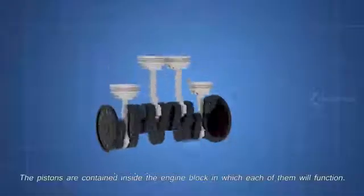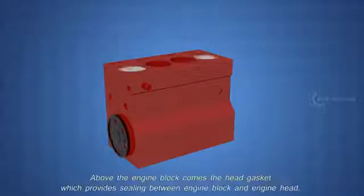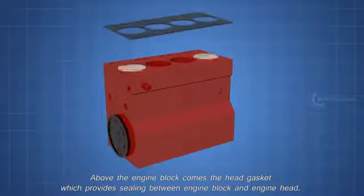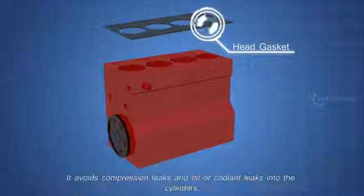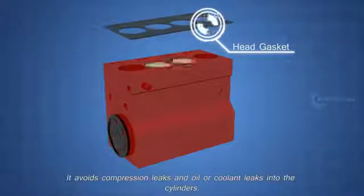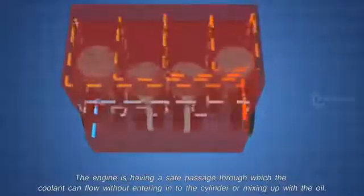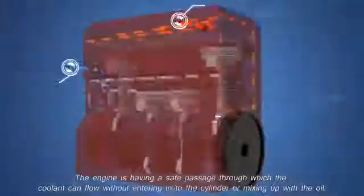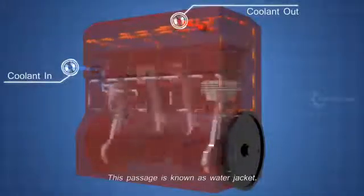Now, let's see how these parts work together. The pistons are contained inside the engine block, in which each of them will function. Above the engine block comes the head gasket, which provides sealing between engine block and engine head. It avoids compression leaks and oil or coolant leaks into the cylinders. Above that comes the engine head. The engine has a safe passage through which the coolant can flow without entering into the cylinder or mixing up with the oil. This passage is known as the water jacket.